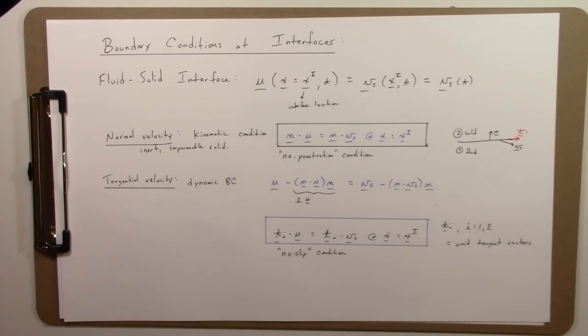We're not going to focus on these particular specialized cases of polymeric liquids or moving three-phase contact lines very much at all, and so the no-slip condition can be assumed to hold whenever viscous effects are included. So you say, well, when does the no-slip condition not hold?